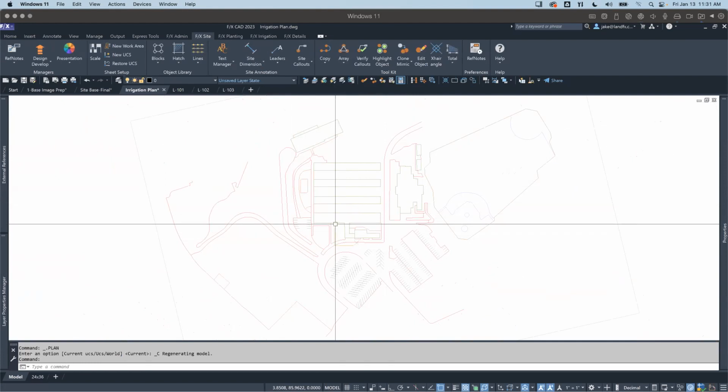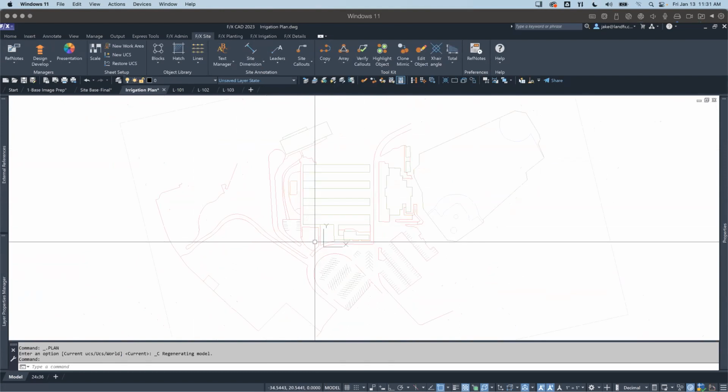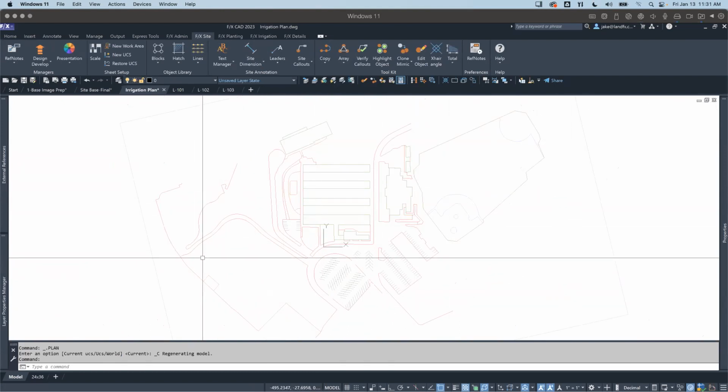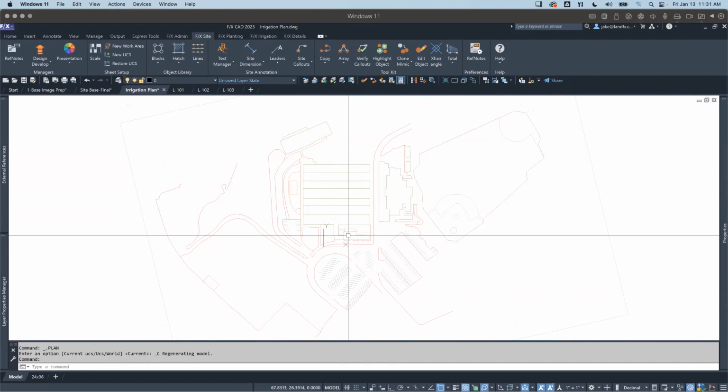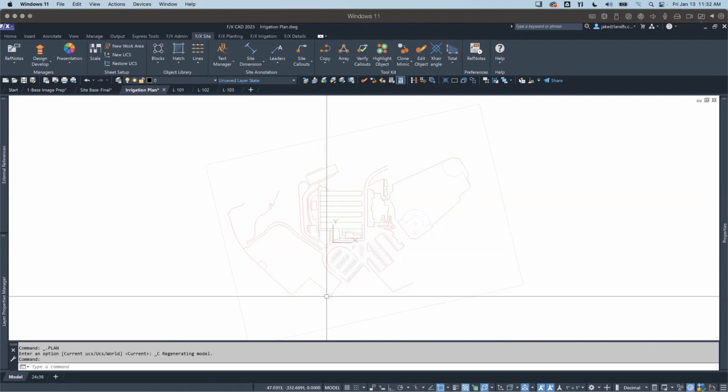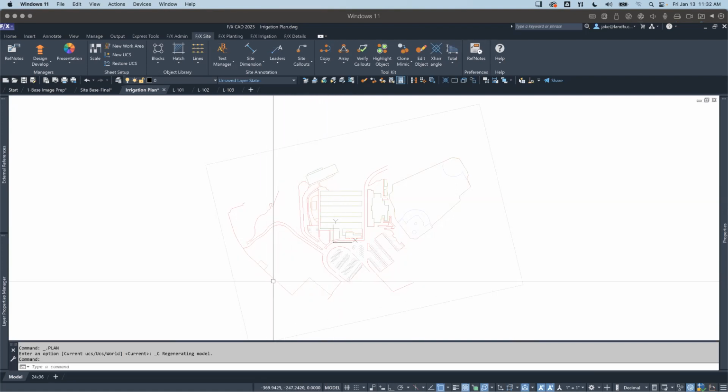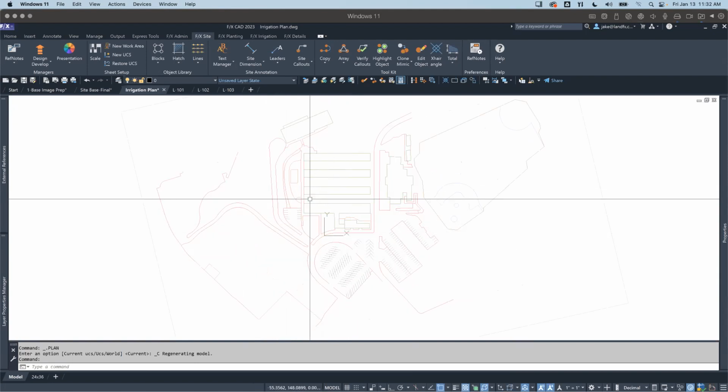Okay, so I have these different UCSs now that I can tweak and use as I start doing my design. In general, when you're doing a plan, and let's say this is going to be the entire site, and I have these different larger and smaller areas, I might need to show the entire site at a scale on a plan just to show it, but that's really not where the detail is coming into play. It's really up to the specific area that you should be designing to. So what that actually looks like and how much I can fit on a sheet is still going to help determine what scale we use as far as design is concerned, right?